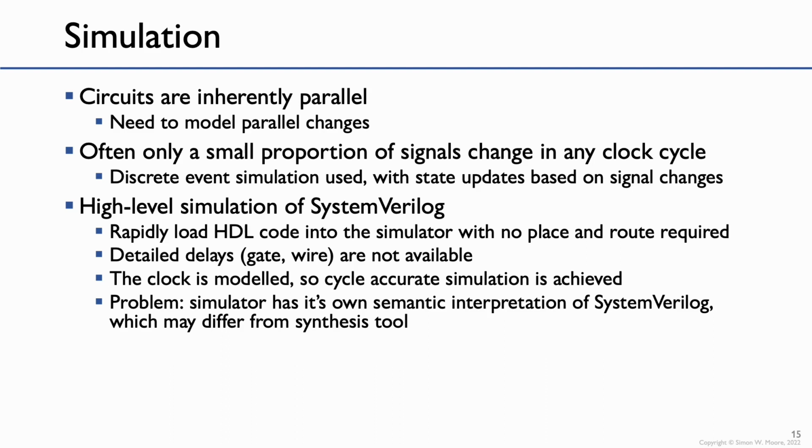There are, however, problems with this form of simulation, and in particular, the synthesis tool and the simulation tool may have slightly different semantic interpretations of the SystemVerilog. Unfortunately, the semantics of SystemVerilog are not all that well defined, and actually this can be rather problematic.